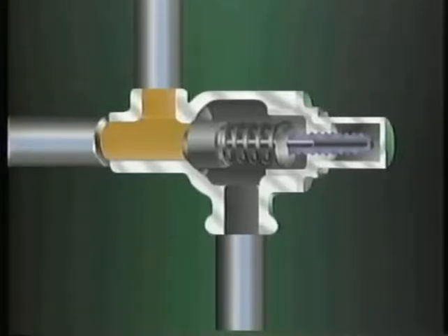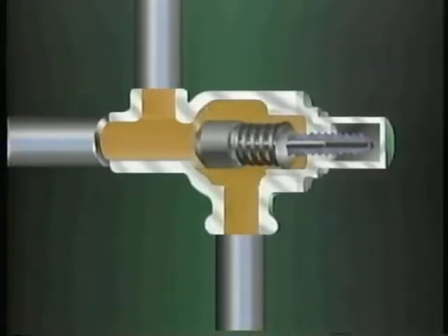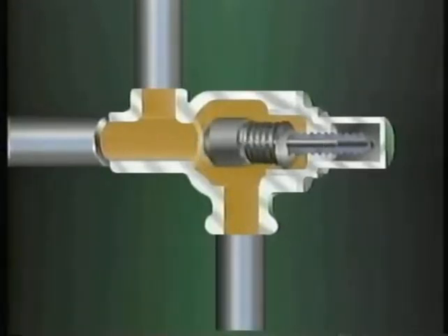Generally, a relief valve is set to open when the pressure in a system reaches a preset maximum safe pressure. If pressure in the system reaches the limit, the pressure on the disc begins to overcome the tension on the spring, and the disc begins to lift off of the seat. As this happens, the pressurized fluid is released through the valve outlet back to a reservoir. If the pressure in the system continues to rise, the disc will continue to lift until it has risen as far as it can go.